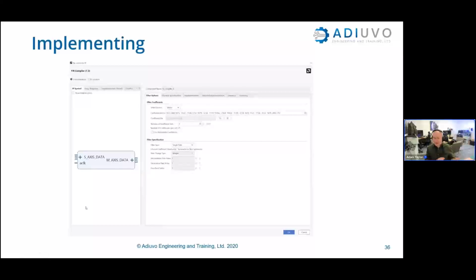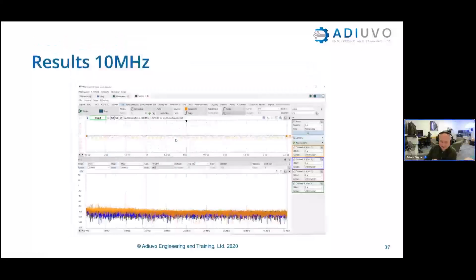And like I say, I don't have much on that just because I had to work out how much to keep up, not putting this out as a webinar. But there are 4 or 5 projects on Hackster that we've done where we talk about how to design filters and work through them. But understanding how to generate these coefficient vectors and quantize these coefficient vectors is really important and a key for our FPGA designs.